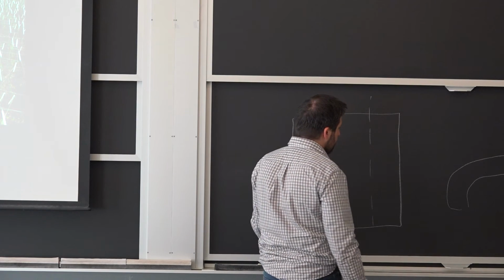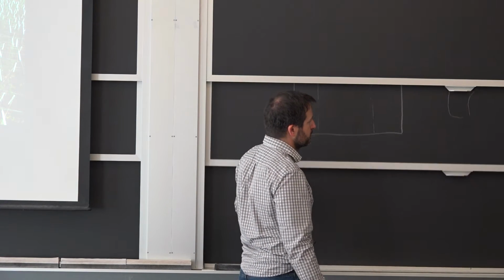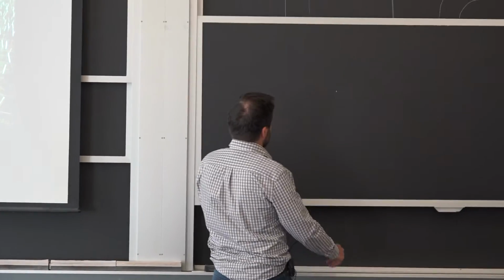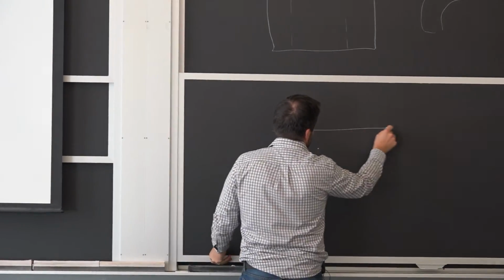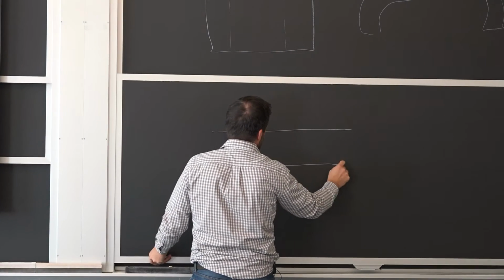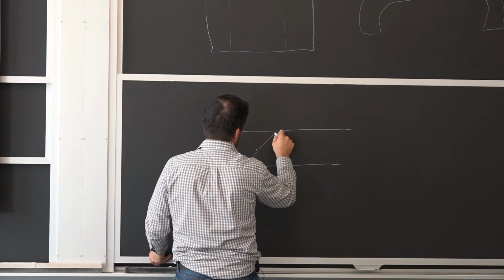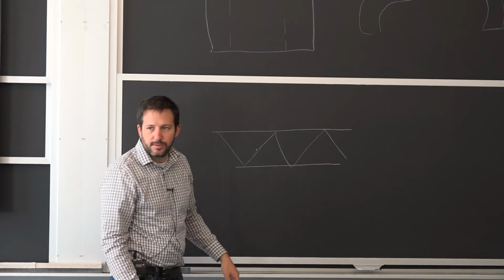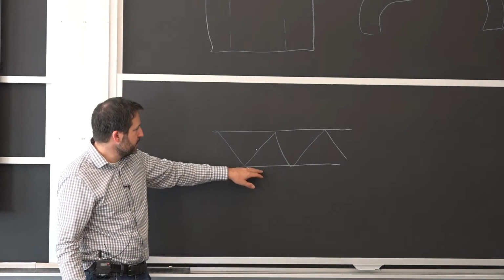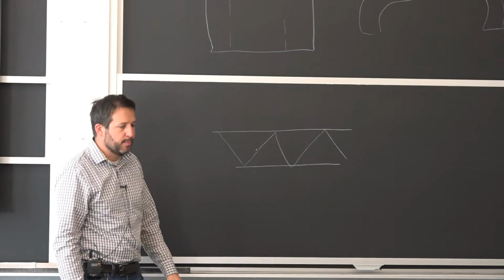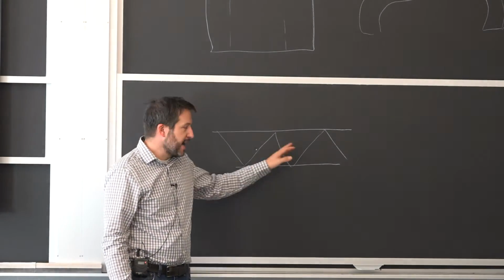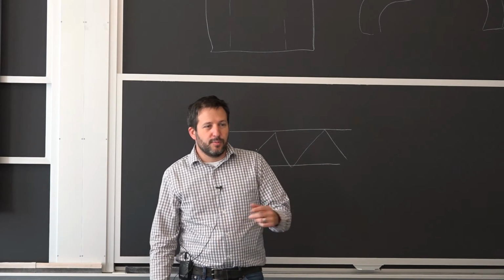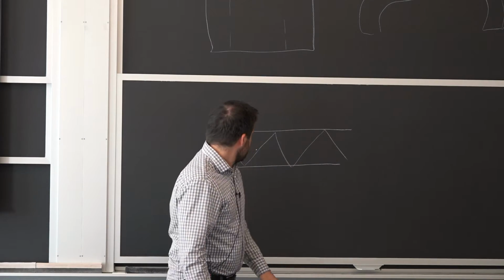So the way the joist work, we call them top chord and lower chord. So you have two big members, and they have to be connected with diagonals to make sure that the shear force is transferred. So you get tension on the bottom, compression on the top one, and those diagonals, one of them carries tension, the other carries compression. So it's alternating this way. The very first one